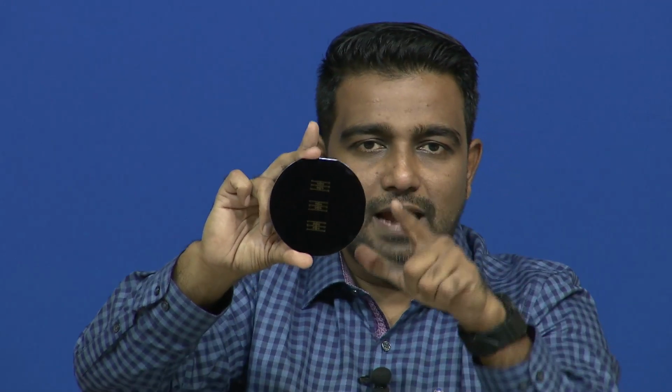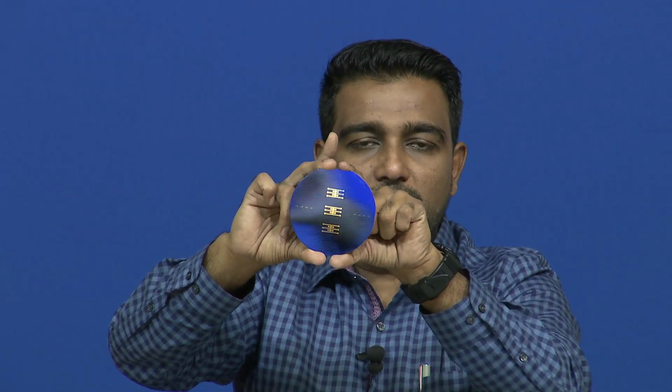The flat can be at 90 degrees as shown in this wafer, it can be at 180 degrees, it can be at 45 degrees, or it can be only one single flat. Now, the big flat that you can see here where my thumb is, and there is a small flat right over here. We call them the primary flat and the secondary flat. The primary flat is bigger, the secondary flat is smaller. In some wafers you will only find a primary flat. Again, to distinguish the type of wafer and its orientation, we have the flats placed on the wafer.